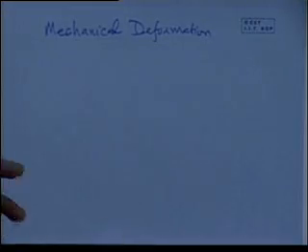So the more we deform, say cold working of a metal and so on, and then we measure. So I took a metal piece, I measured its resistivity versus temperature behavior, and then I cold worked it. I rolled it, deformed it in various ways, and then I took its resistivity again. So I will expect to see a higher resistivity simply because the number of dislocations that have been introduced into it increases the rho r term.